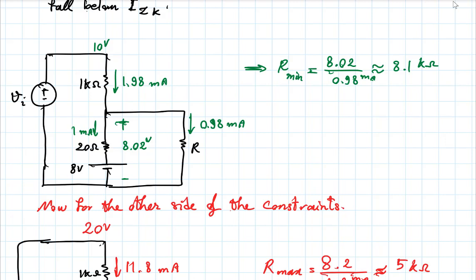If you have 10 kilo ohms for R, then you will get 0.802 milliamps there, right? The Zener current will be a little higher than 1 milliamp. And in fact, you would have to recalculate exactly, because if the Zener current is a little different, the voltage is a little different. I'm not recalculating, but I get the feeling that things are going to be OK.